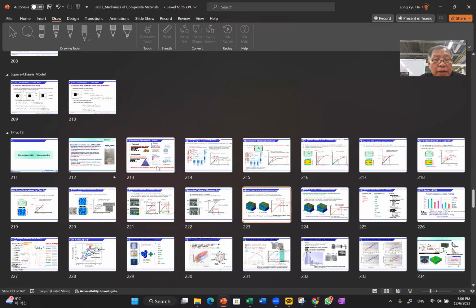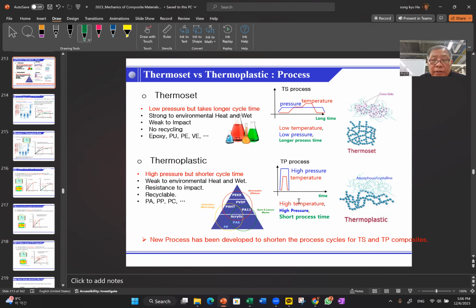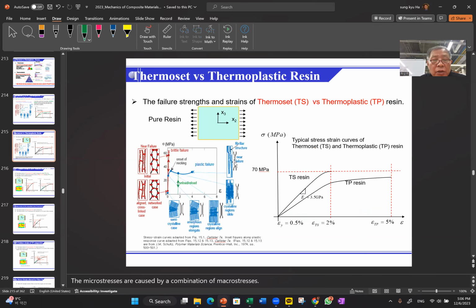So two things: with thermoplastic, the manufacturing process can be quite different, with two different characteristics, and structural-behavior-wise, the high failure strength is very beneficial in composites, and of course thermoplastic is recyclable. That is very important these days. But conventionally, all the way, thermoplastic has a little bit lower strength like this. So they prefer to use thermoset.